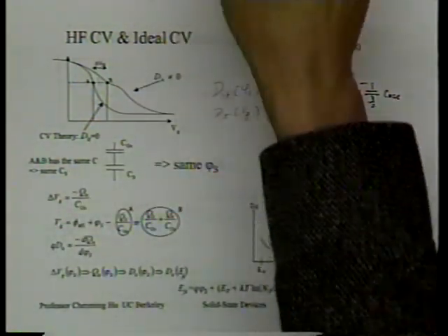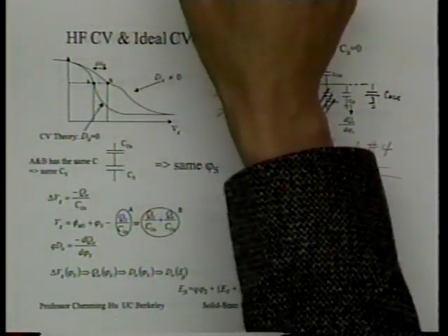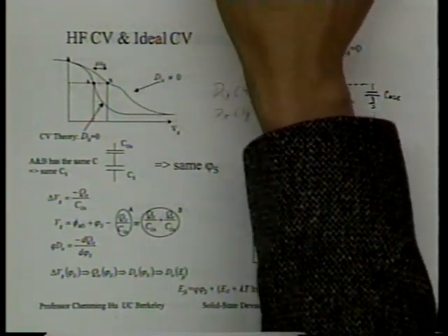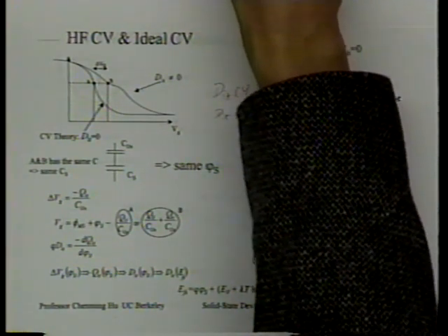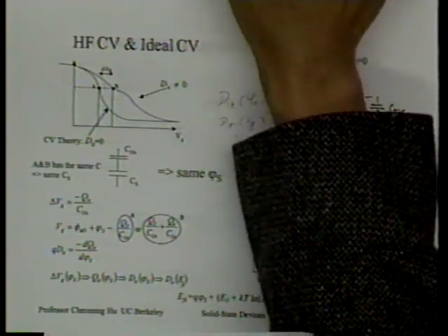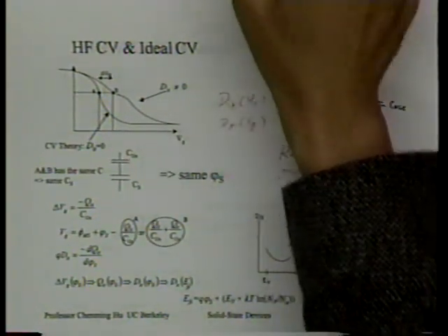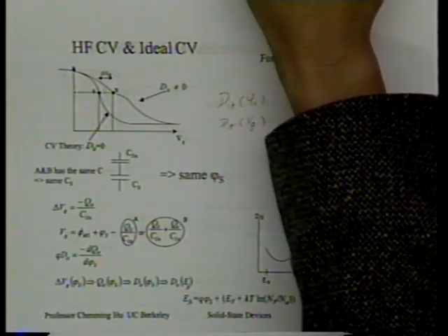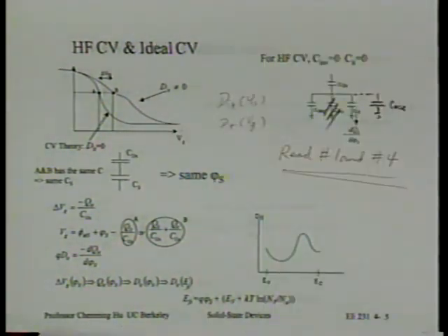As a result, there can be pretty efficient tunneling, right? And therefore, the electrons in the oxide can communicate with the electrons in the conduction band or valence band. As a result, whether it's occupied by an electron or not will follow the same Fermi level as the substrate. That's the meaning of equilibrium, following that same Fermi level.